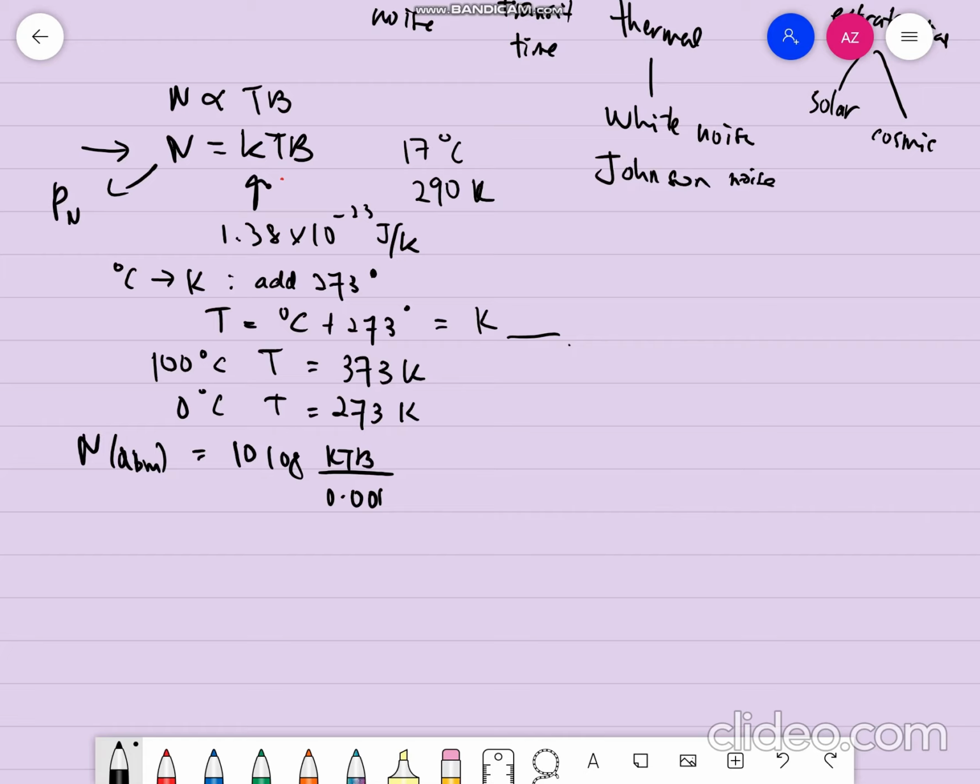Then we will move to the noise voltage, where we have an equivalent circuit for the thermal noise source, where the internal resistance is in series with the RMS noise voltage. For the worst case condition and the maximum transfer of noise power, the load resistance is made equal to the internal resistance of the source. So the noise voltage drop across the resistance will be equal to half the noise source.